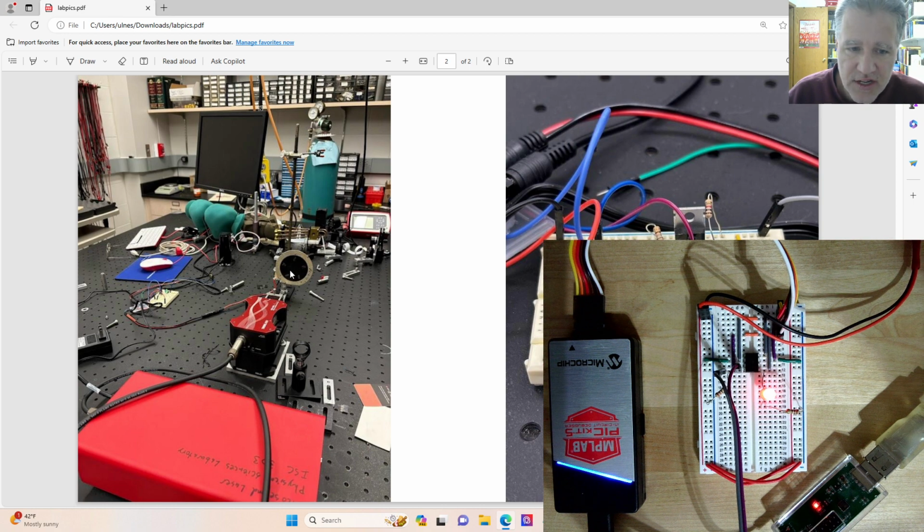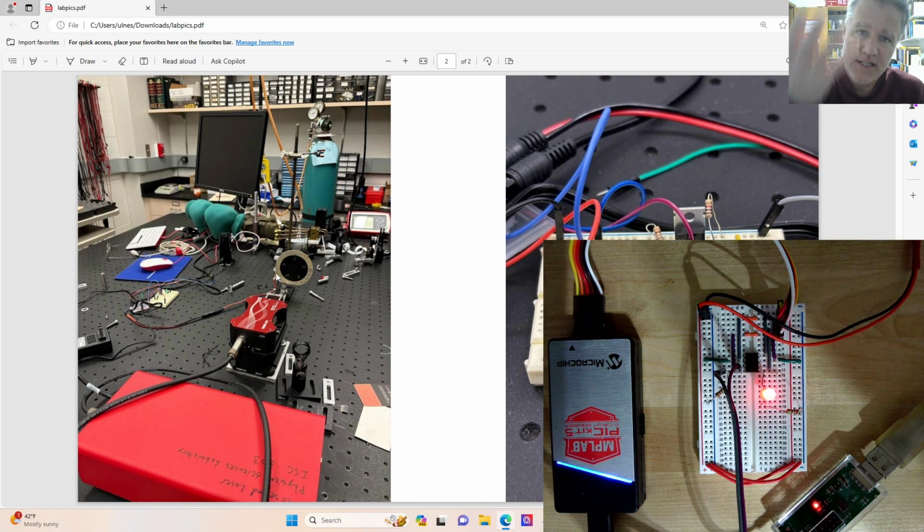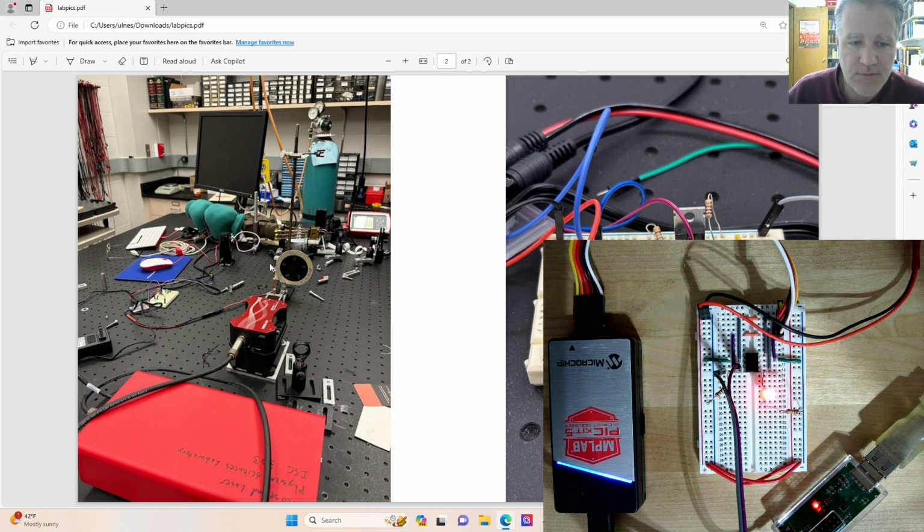The laser's right here. The laser will be on, and the sample's down here. And this is a cooling jacket for the sample. We want to send the light into the sample, but we want to control when that happens. So we have the computer tell the shutter to open. This is a solenoid sitting right here, and that will pull the shutter open when it has 26 volts applied, and then close it when it has 0 volts applied.